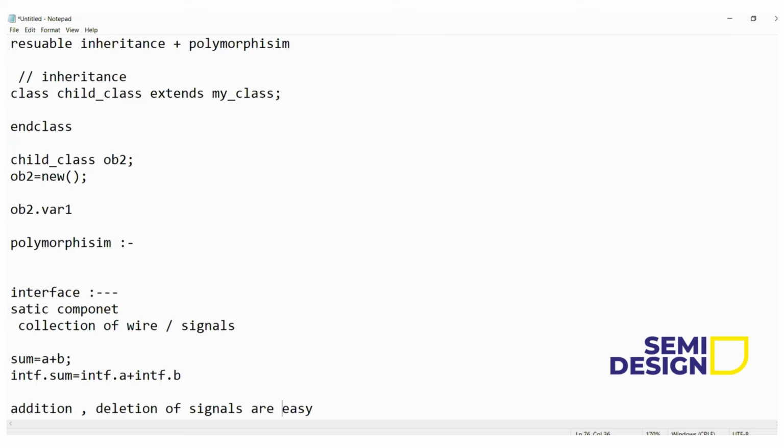Okay. Why logic? I explained it in yesterday's class. What is the advantage of having logic? Well, we don't have to worry about whether it's a register or a wire. And during the connection, we will be connecting those signals to our DUT, so we don't have to think about whether this is my output or my input. Logic can work for input and output, but it will not work for an inout port, because an inout port has 2 drivers and logic has only 1 driver, meaning only 1 direction.